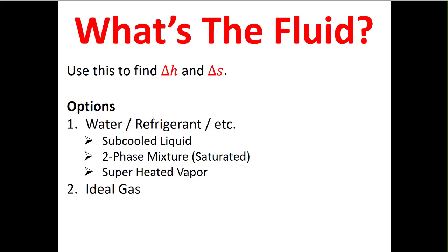We've got an evaporator. That means we're taking liquid and boiling it, right? And we've got a condenser, which means we're taking vapor and condensing it. So phase change is something that we have here. So as we draw our TS diagrams, we need to have a vapor dome on there. And then we'll have to ask ourselves, what's the phase of the fluid?